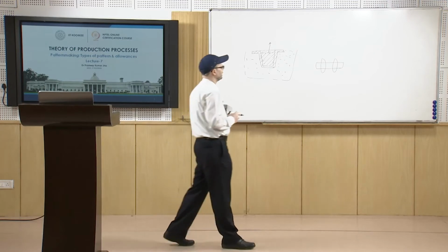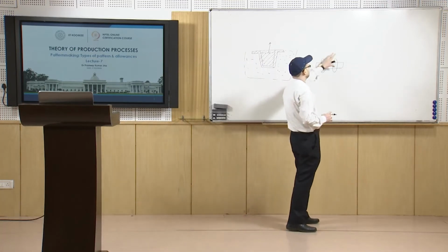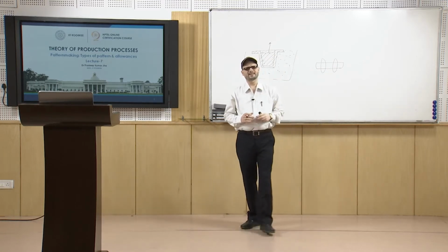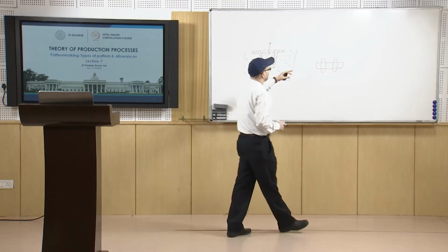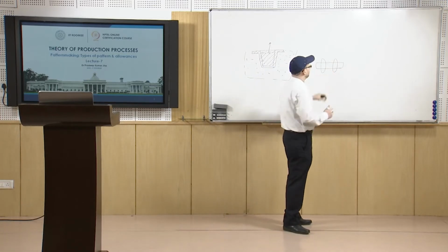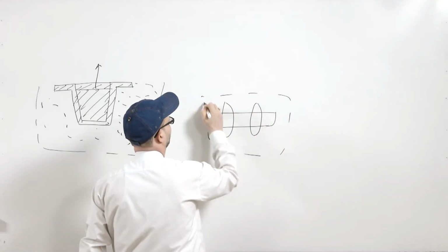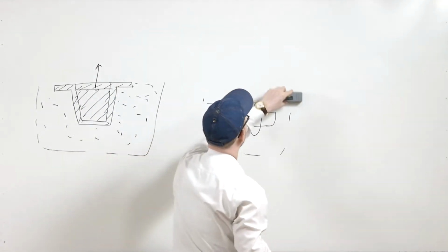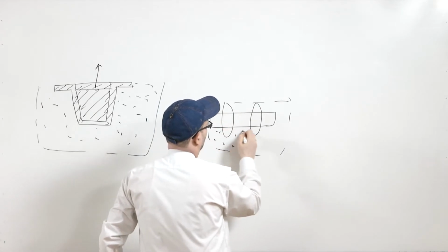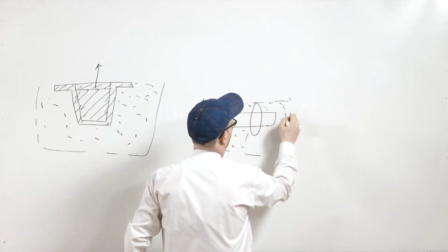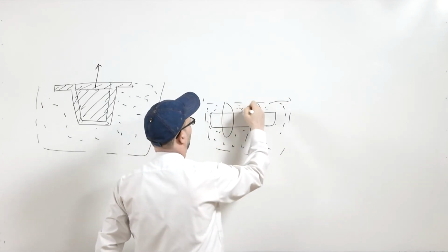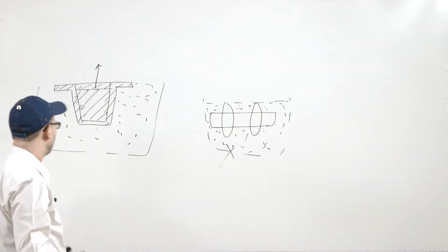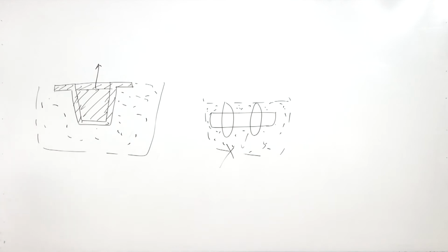If you try to ram the sand, you will not be able to take the pattern out once you have rammed the sand, maybe even in the drag portion, because there will be many places where you will have damages. So, it is not possible to make the cavity for such shaped patterns.